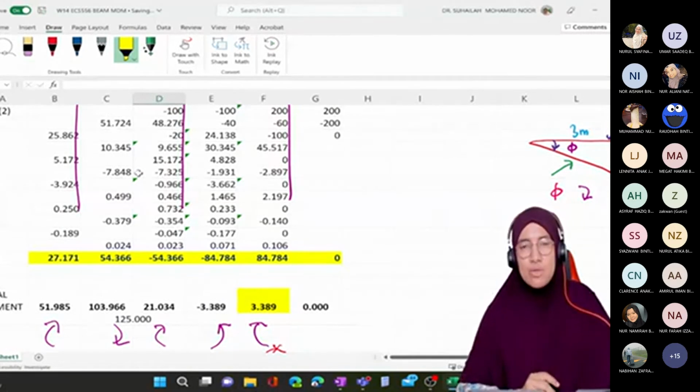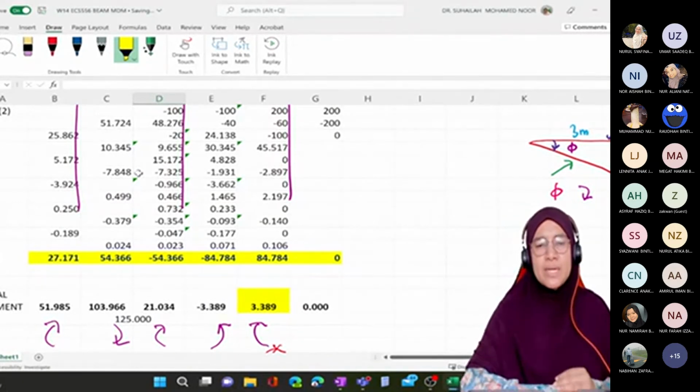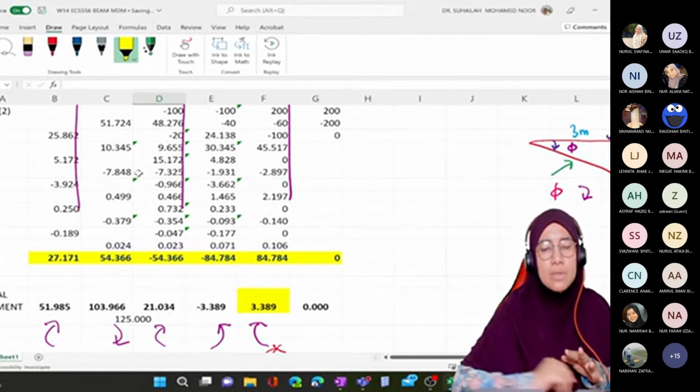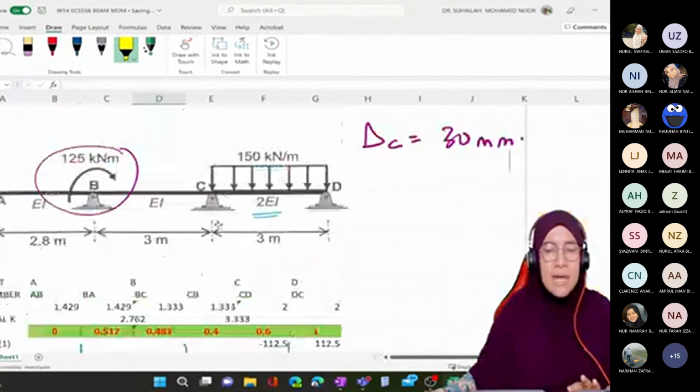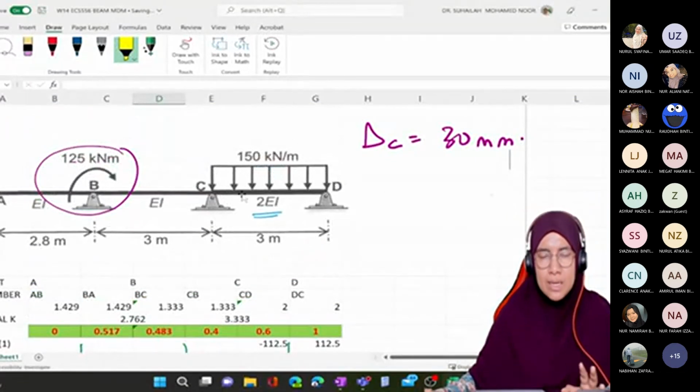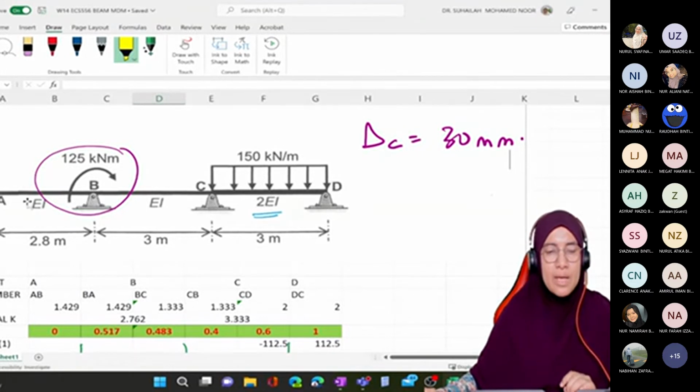But to get the salient point, the maximum moment in the bending moment diagram, if we look at this beam, we just need to consider member CD only to calculate the shear force and identify the shear force diagram, so that we can identify whether member CD has maximum moment or not. For A, B, and CD, there's no need to draw the shear force diagram because we know there's no maximum moment here.